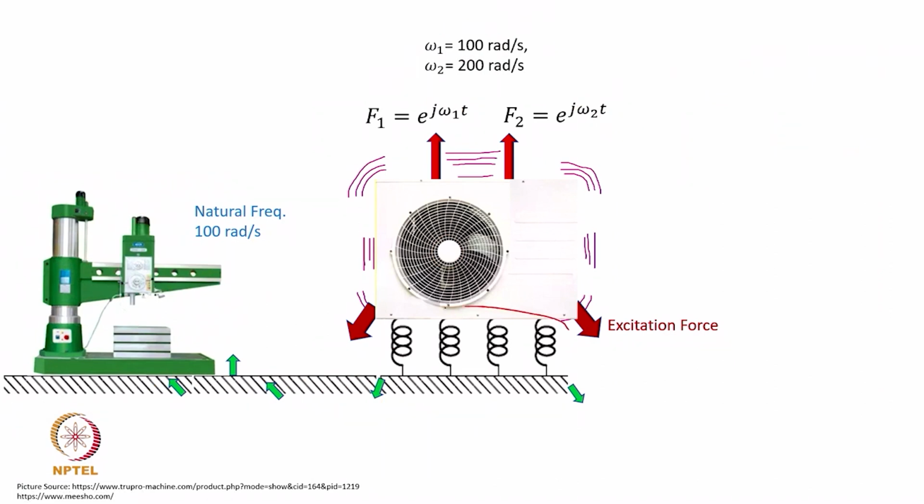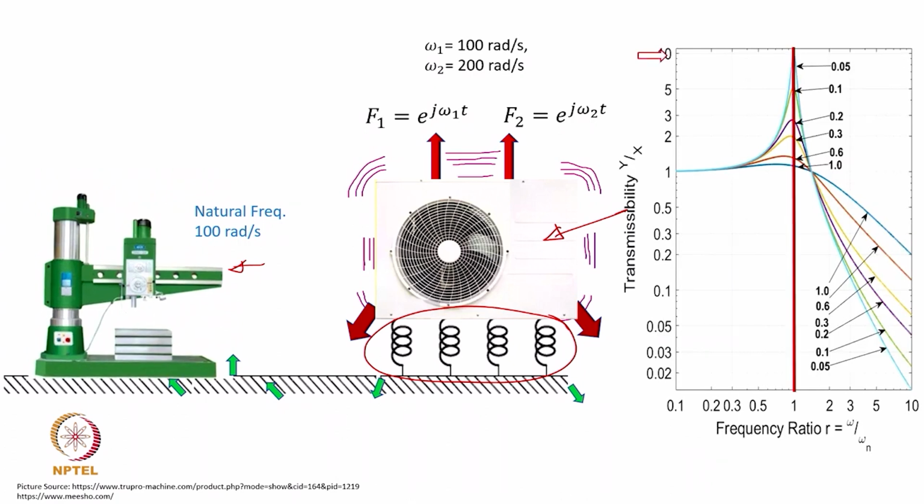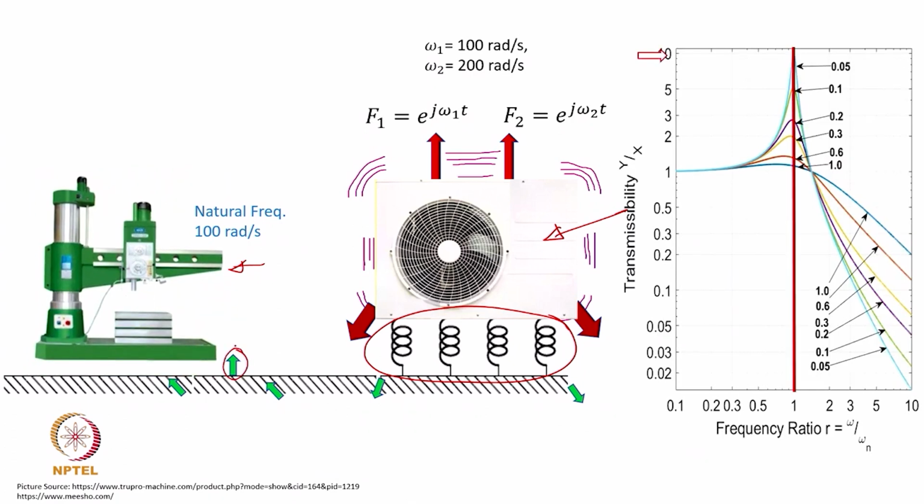You have already taken care of the force transmissibility by properly designing the isolators of the source machine here, but your target machine already has a problem, and therefore I will have to redesign so that this excitation amplitude does not cause larger amplitudes in the target machine. So, what you do is you put this machine as well under some isolation. For the same mass with the original k, which could come from here only, you have put an additional k here in series now.